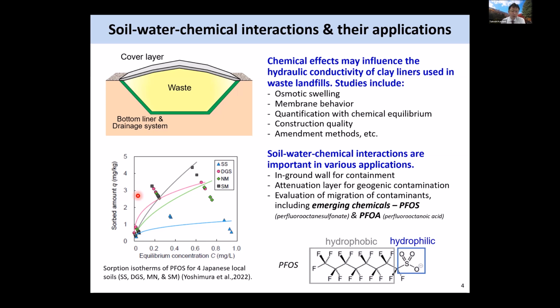The sorbed amount is the PFOS attracted to the soil particles that will not be transported by the movement of the water, so it is trapped on the soil. So if we have a high sorbed fraction, our PFOS will remain in the soil and will not be transported with the groundwater. So we may not have a severe groundwater pollution problem, but we might have a problem with soil pollution or soil contamination. So the soil becomes more polluted when the number is higher. Yes. And if the number is lower, it means most of the contaminants are being taken by the water.